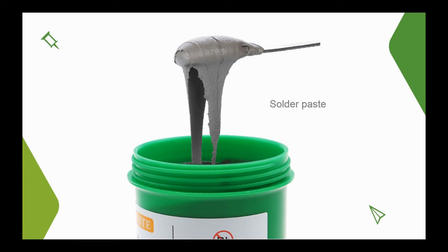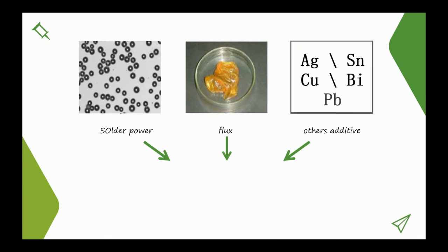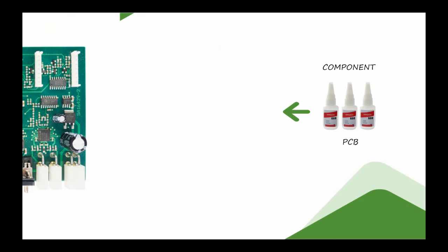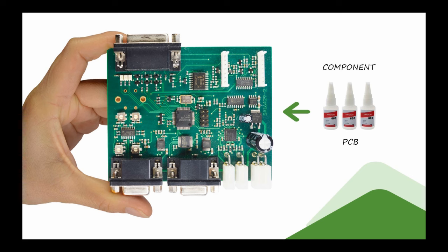Solder paste is a new material accompanying SMT production development. It is a complex system made of solder powder, flux, and other additives, blended together. Of course, the additive composition depends on its needs. Solder paste has a certain stickiness, so it can adhere to electronic components at a given position. While the temperature rises, the electrical components and PCB will become solid and form a permanent connection.